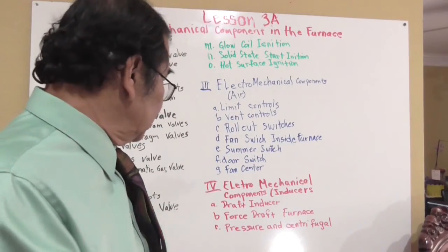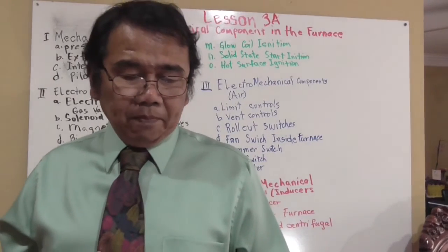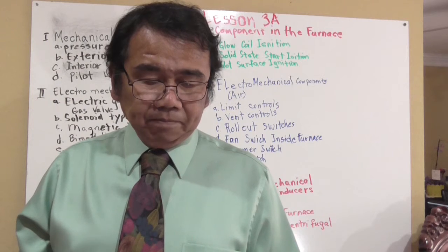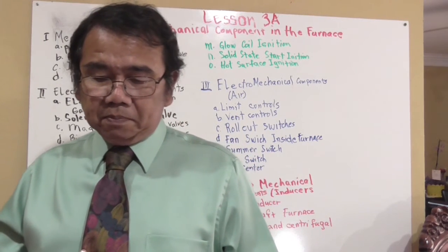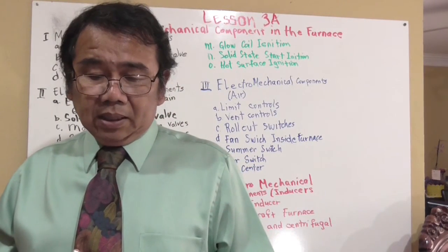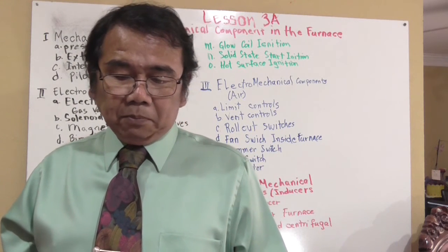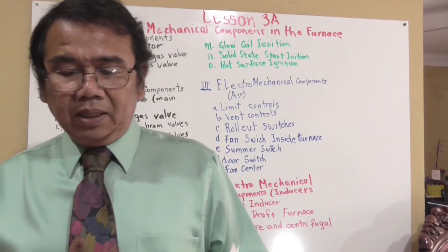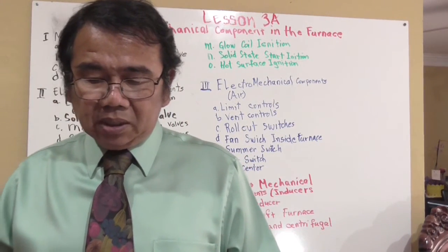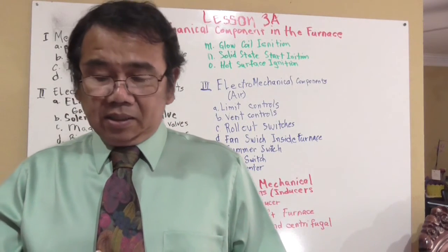And then we have the forced draft furnace. Forced draft furnaces are much rarer than induced draft furnaces. A forced draft furnace pushes the products of combustion through the furnace. If the furnace is forced draft, it will always have sealed combustion. Sealed combustion means that the entire area where the burners are is sealed off.